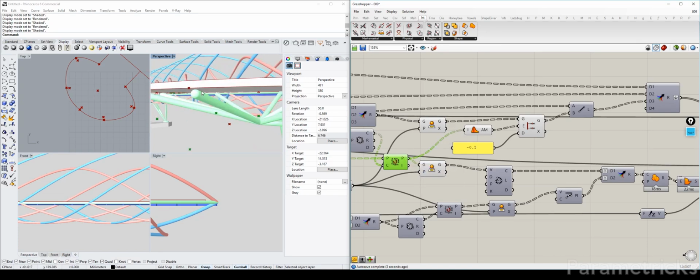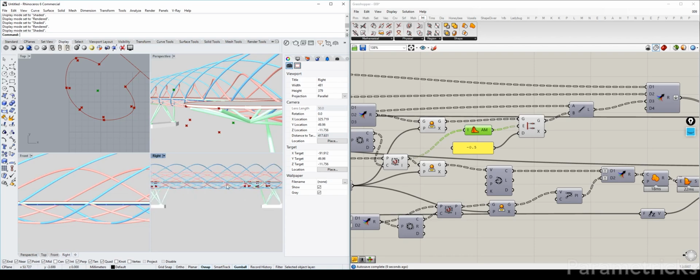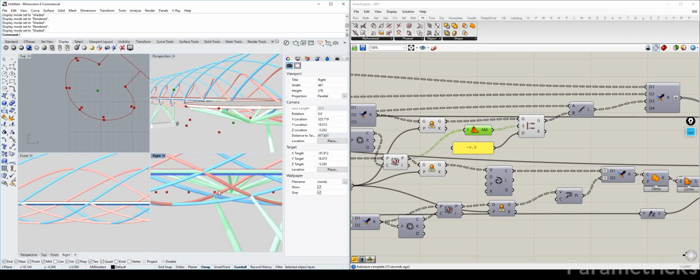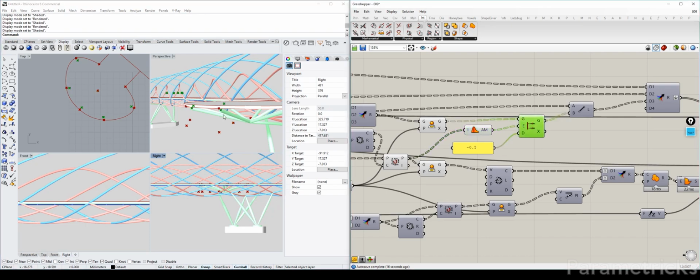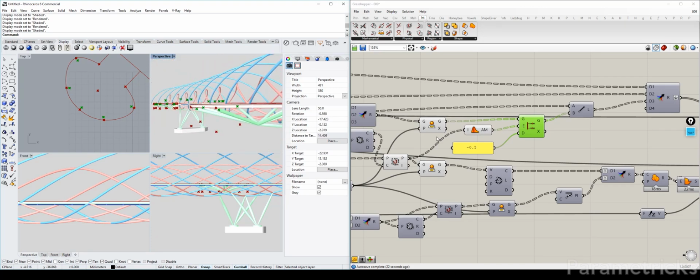As you can see, it's sort of not touching, and that's because the average point is not on the same plane as below the deck, and therefore moving away from a geometry that's not on the same plane will modify their x, y, z coordinate system. Whereas if you move it on the same plane, they'll just move on the x, y coordinate system. So that's something to take into consideration when you're trying to do the averaging. So instead of taking it from this, this will eliminate that problem of changing the z height, because they're all from the same height. Now, if I take that, let me enable this.